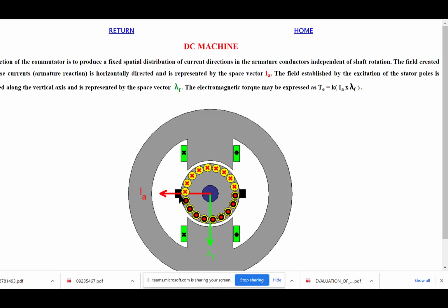that's where it essentially flips the direction of the current in the rotor so that the X's always stay on top and the dots always stay on the bottom. And that's what a commutator does. It's a mechanical, electromechanical diode rectifier, really, if you want one way to think about it. It keeps the current going in one direction as this rotor moves. And it uses that principle of brushes riding on copper slip rings, except the slip ring is segmented around the structure.